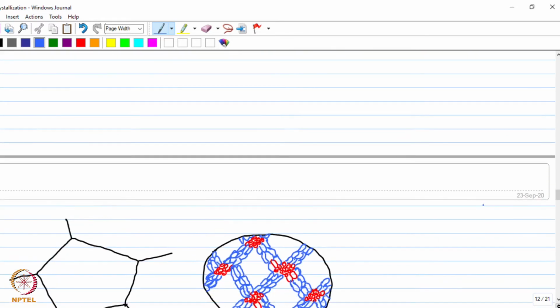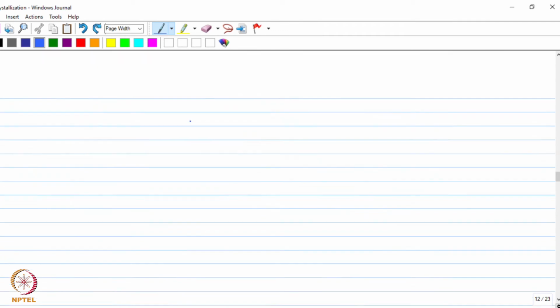So the process can be depicted with this diagram. So you have boundary sliding in the beginning, as I said before, and this sliding can be stopped at these triple points, at the grain boundary triple junctions, and therefore stress concentrations will develop around this.